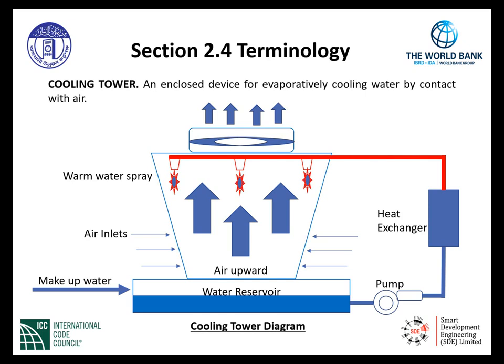The water reservoir must be at a certain level, not to be below the pump level. Therefore, by evaporation due to the atmosphere, makeup water is required, and as you can see on the left-hand side, we do have a makeup water supply to keep the water reservoir at that precise level to keep supplying water to the process to cool down heat exchanger and chilled water condensing water.